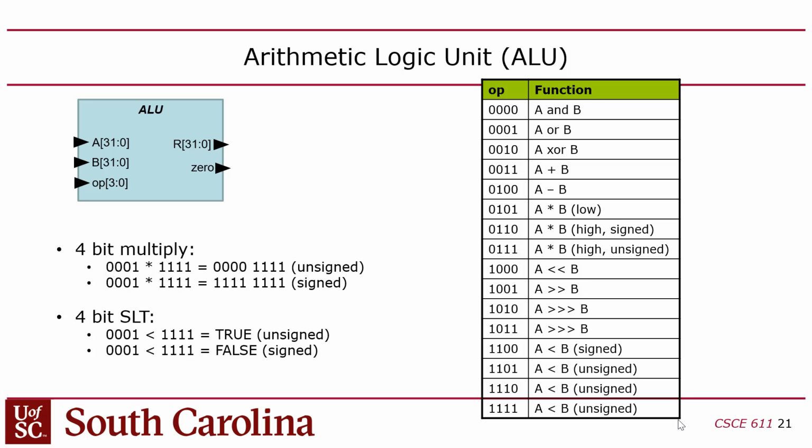And then we have multiply. There's the low multiply, and then of course the two high multiplies that correspond to mulh and mulhu. Obviously that's different from MIPS. MIPS had a high and low register when you did the multiply to produce 64-bit results.